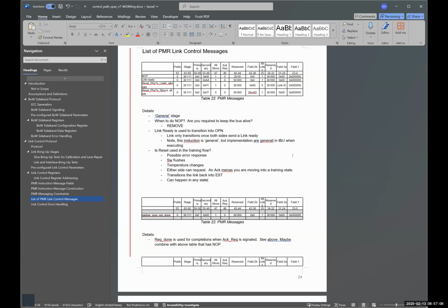Yeah, so for me also it was only link, but I think there were some implementations. Maybe Paul can also chime in, but there were some implementations where you could have a link that is formed out of multiple slices, and each slice could carry data independent of the other slice. So there were some implementations that wanted support for that, and I think that is the whole reason why two separate resets, one for link and one for slice, got introduced. Okay, so we should probably say that.